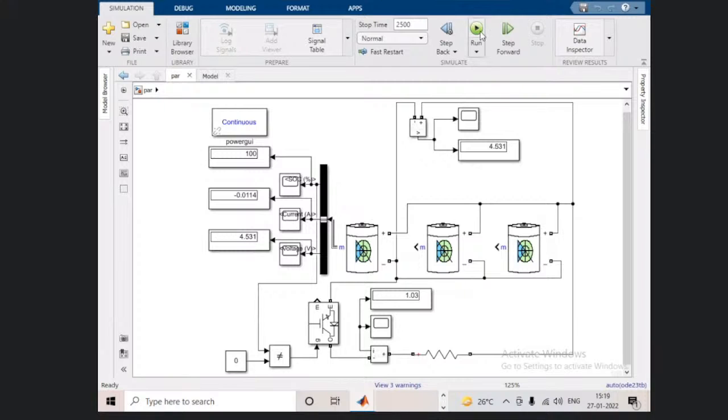Now we will get the correct results. Now you can see. Is it visible now? Hello? Yes, sir. You can see here the voltage is the same, 4.003 and 4.003 over here also. And the same current capacity, 0.3032, has been tripled over here. So let us check: 0.3032 multiplied by 3 is correct, 0.9096. So we are getting the correct answer. Understood, everyone? That is how series connection and parallel connection work.